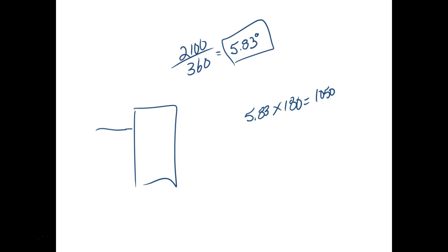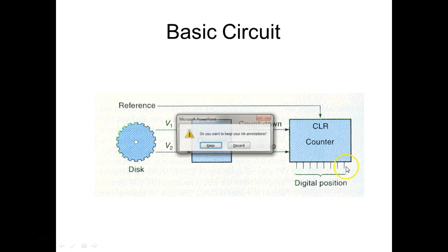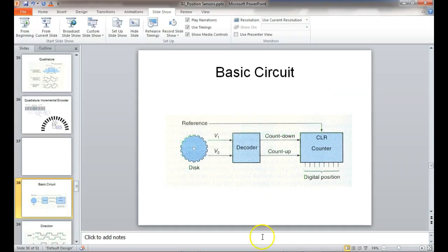And this gives us what? This gives us all three. That's why it's got so many wires coming out of the back. Not only do you have to control the motor, you have to power up the encoder. So the encoder's got its own ground and its own power, and then you've got the two channels coming out of it. Direction. So notice, we're doing all that right here. Then we played around with position.